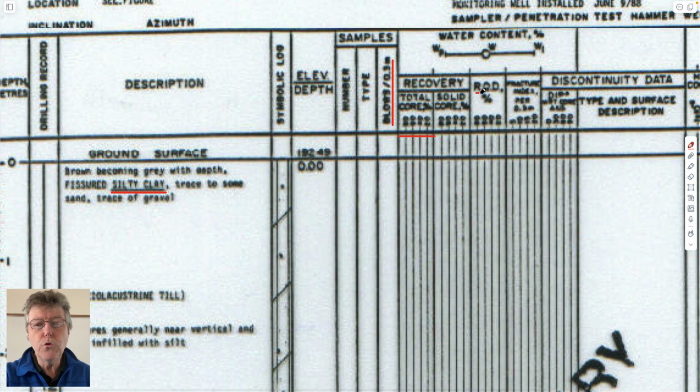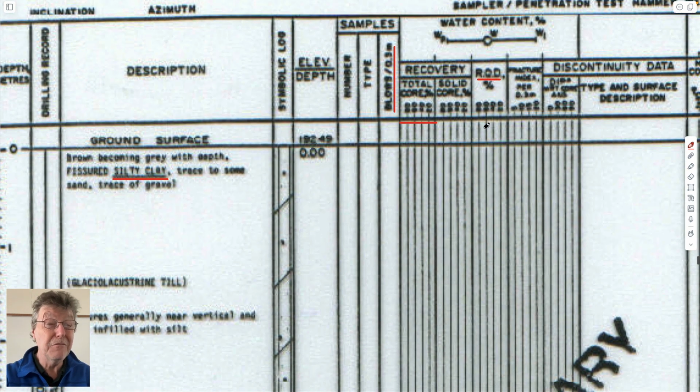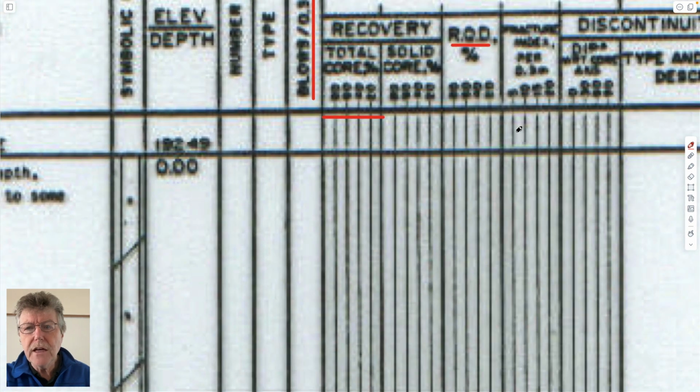The so-called rock quality designation, RQD, is the percentage of pieces of core which are bigger than 4 inches, just as a measure of the quality of the rock. Again, not for groundwater hydrology, but for constructing tunnels, to be able to evaluate strength.